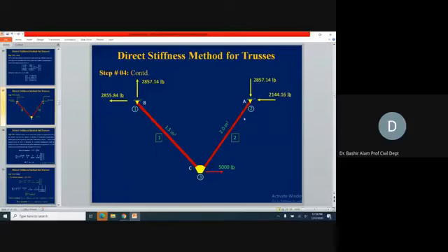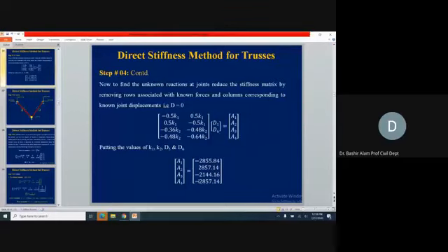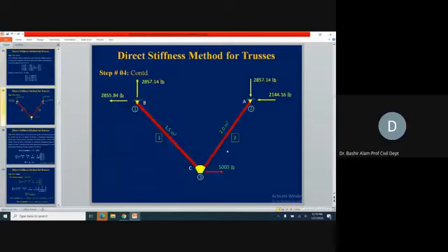And this last one, if you see here, it is negative. So it means opposite to the D4 direction, and it is minus 2857. So here we see 2857 in the downward direction. Now, member one force, you can find by taking the diagonal, the resultant of these two forces and inducing it here, which means this is coming in tension now.